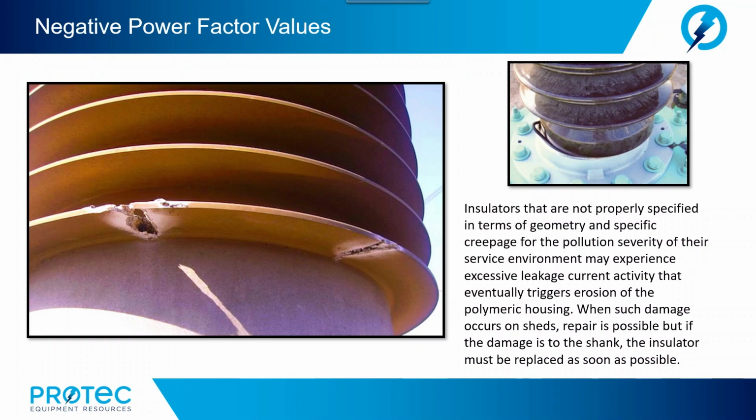Now, let's also take a look at negative power factor values. They do occur from time to time. Creep currents inside an insulation system, or more commonly on surfaces, create change of potential distribution that may give increase or decrease dissipation factor, and in some cases also negative dissipation factor.